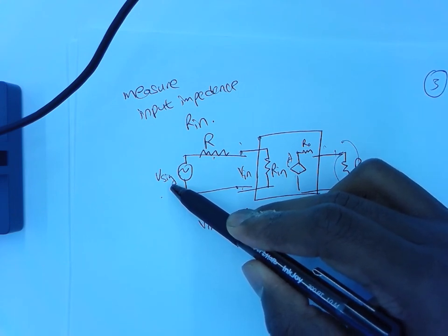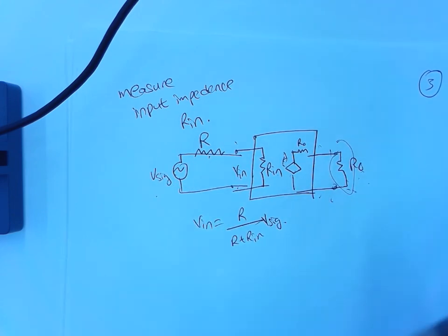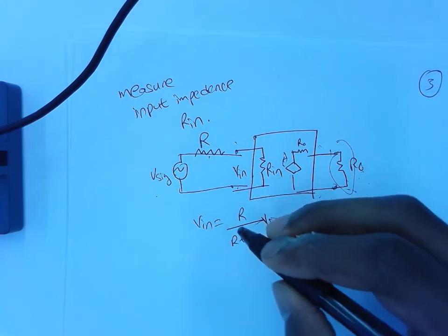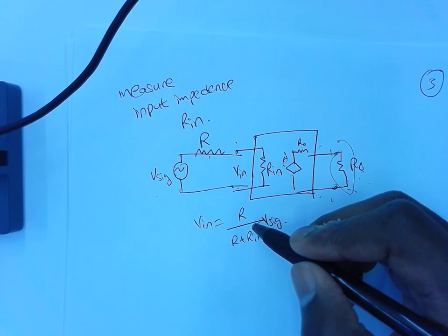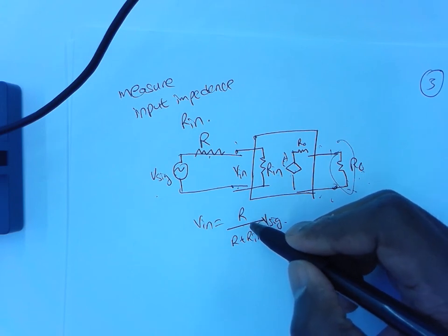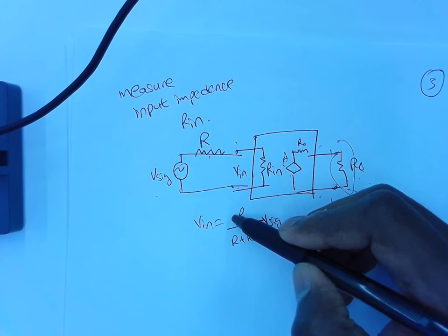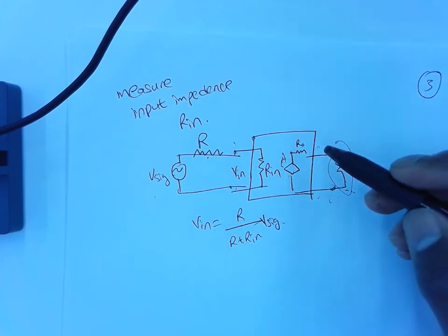I didn't know you were using a multimeter in that case. I thought you just used that formula. Right. So measuring voltage is still accurate with multimeters, right? But if you have very high input impedance, then you cannot accurately measure the input impedance using a multimeter. So you can measure voltage accurately, so you measure that. And then you just solve for R.